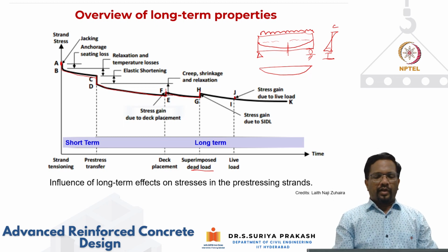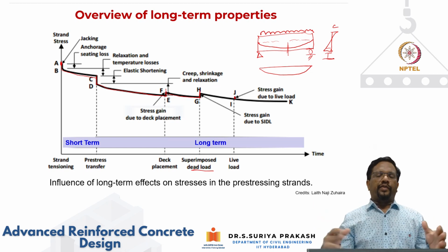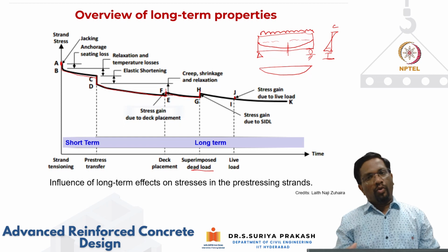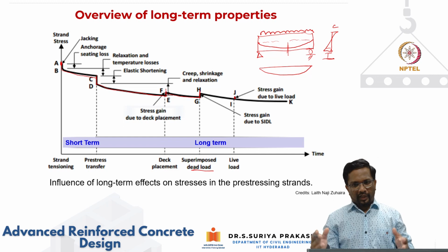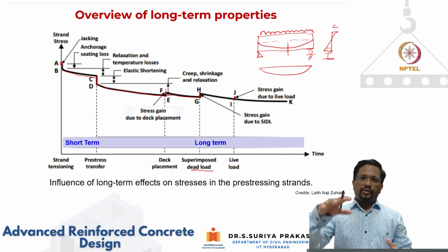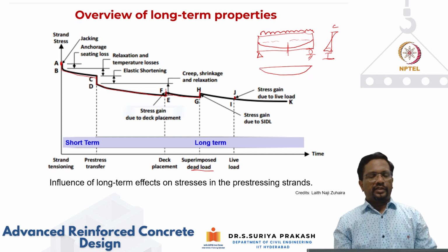However, even for regular RC systems, especially in columns and long span elements, the effect of creep will lead to more deflections, especially in beams and slabs. And in the columns you can also have additional stress effects that we will discuss in due course.